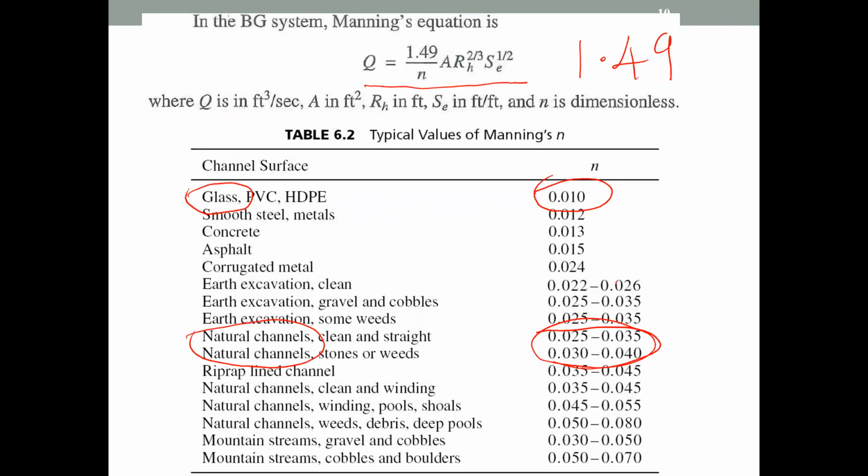Right. So you see what we are interested to find out. In a hydraulic design, basically what we need to understand is what should be the cross-section area. Why is it? The cross-section area affects the excavation that you have to do. Then if you are going to use concrete, then what is the amount of concrete that you have to use for this channel, right? So all these decisions have to be made based on this cross-section area that you design, right?